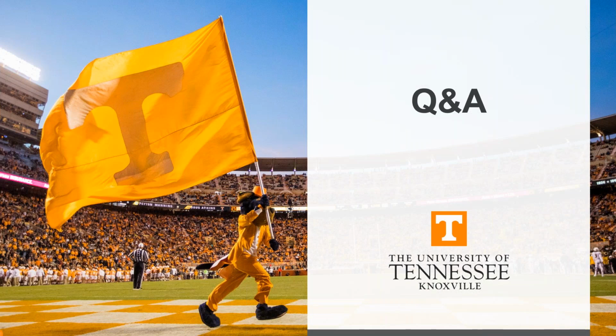We have another question here. It's how to set the zero moment point at a single plate connection. So that's really within the software. When you select a model type on the member, you can adjust where the load is being applied, and basically where you're applying that load will set the zero moment point. So you can adjust that right within the software itself. There's also a nice feature to check that you did that right. I think you have to turn on the wireframe, and you can see the moment diagram on the members. Exactly.